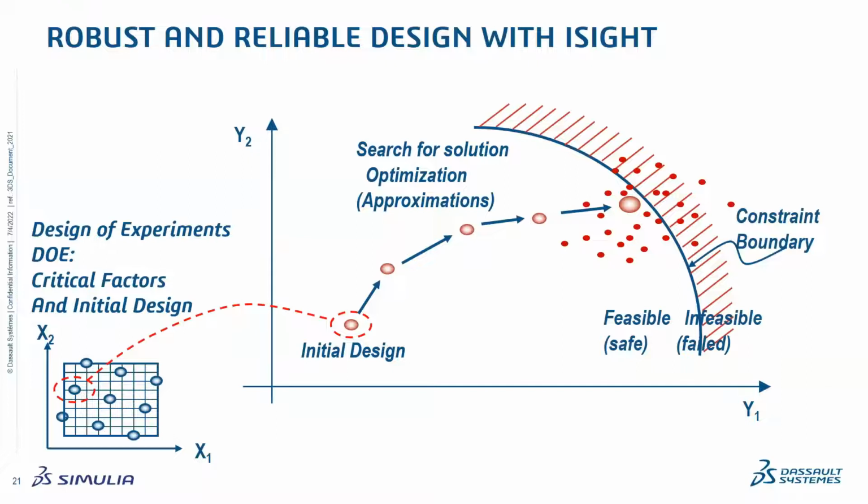So then what would have happened? It might fall on the other side of the constraint boundary. If the sheet metal thickness that you have considered is around 5 mm, but ideally it's around 4.95, or maybe a little change is there, that delta change. In case that delta change is added into the model, what would happen? Whether it will still be within that safe zone, or feasible zone, or whether it will fall on the other side of the constraint boundary. So that you can understand when you try to run a reliable study, or Monte Carlo study.